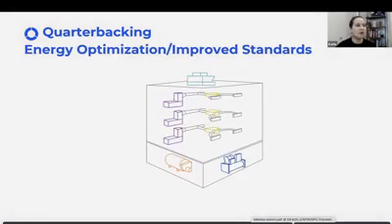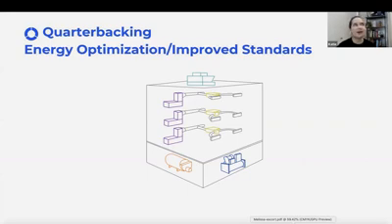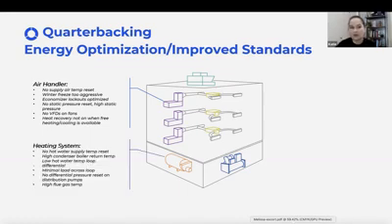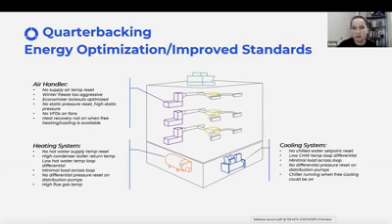The other thing is, yes, we talk about energy savings. We find things that are broken, like our economizer is not operating when it should be. That's a problem. But there are also opportunities that can be highlighted with FDD, because they know what your systems are, they know how they operate, they know how they're supposed to operate, and they can quantify the cost. They can say things like your air handler doesn't have a reset, and if it did, you'd save $10,000 a week or a month or whatever that number is. Your heating system has a low return temp and a low hot water temp differential, so you're not getting great efficiency off of your boiler.